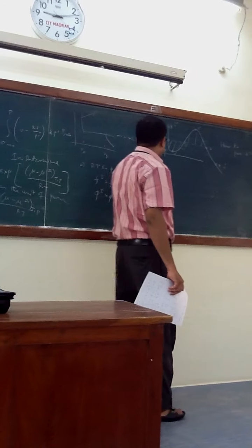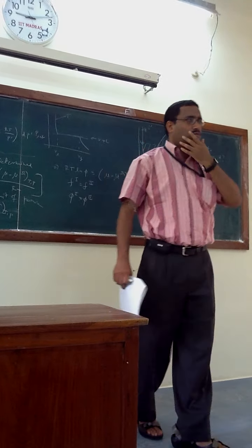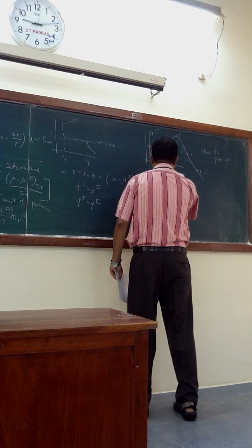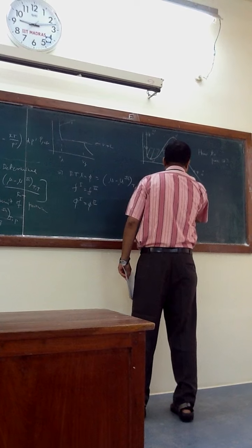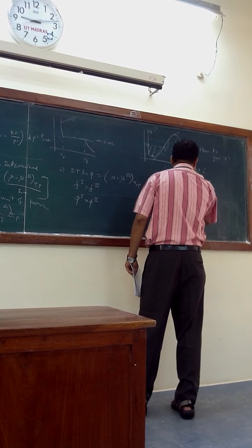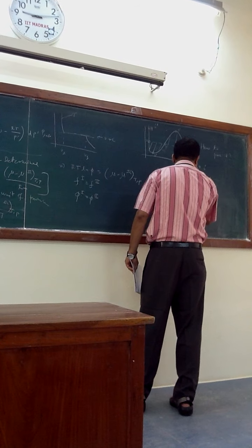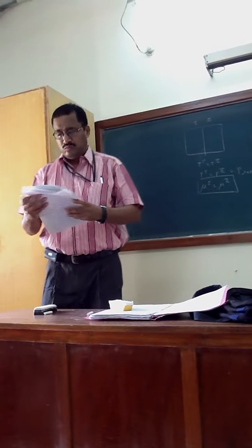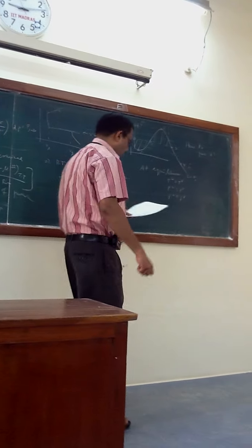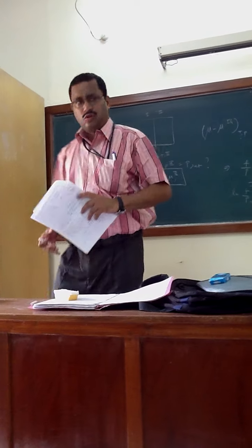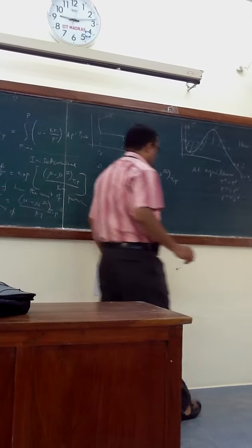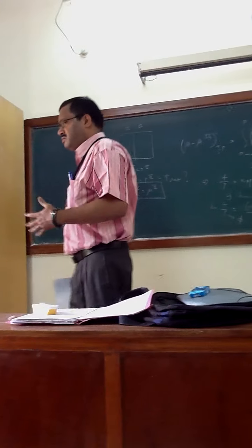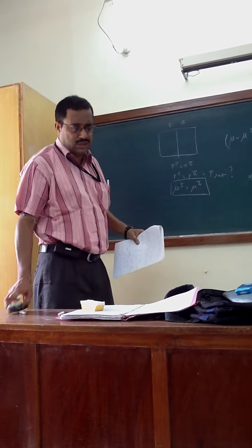And we know that at this point where we have thermodynamic equilibrium with two phases, temperature of vapor equals temperature of liquid. At equilibrium, on the 2 to 3 line, temperature of vapor equals temperature of liquid, PL equals PV, and FL equals FV. So the basic equation, mostly we'll be using this. This you can treat as the governing equation because temperature and pressure are all known, and also the saturation pressure, how to determine it, is all discussed in a short while.